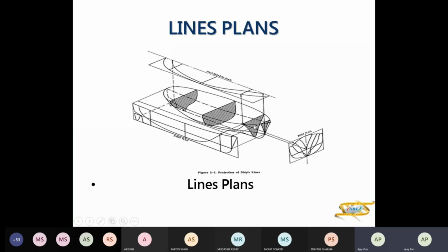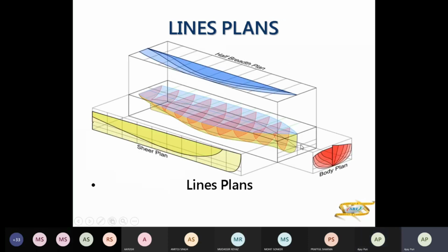Forward and aft curves will be small, those projections. Like this, you have 11 sections, so the curves will be like this. This is 0 and that is 10. These are the various sections, showing what curve they make with the hull, as the planes are projected. The aft end is here and the forward end is here.